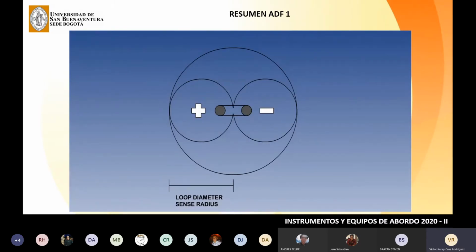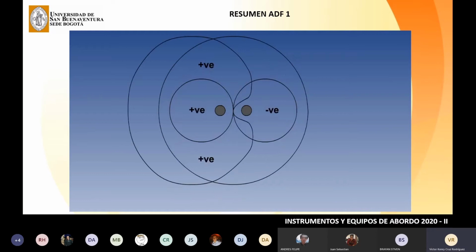Consequently, the radius of the polar diagram of this single-pole antenna is equal to the diameter of each of the loop antenna circles. It is arranged for the field from the sense antenna to be in phase with one of the elements of the loop antenna. Here we see it is in phase with the left-hand element. The resultant polar diagram of signal strength is known as a cardioid, which means that it is heart-shaped.